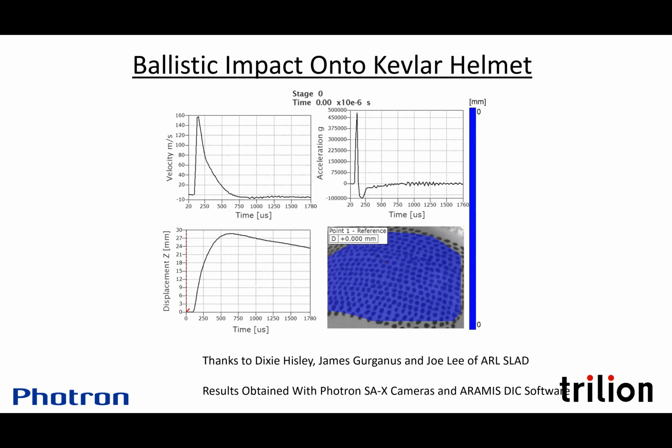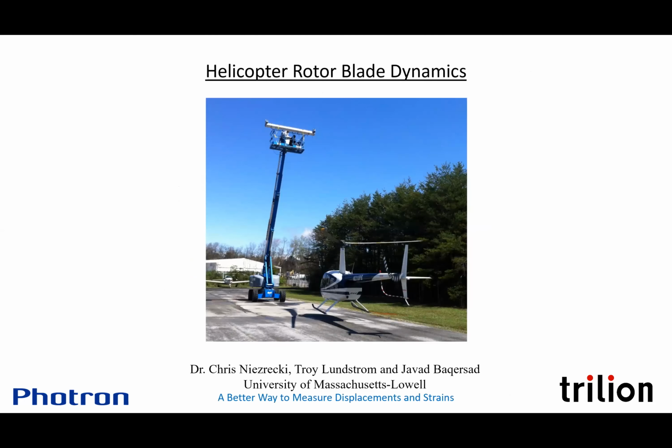ARL SLAD, Dixie Hisley, and James Gerganis and Joe Lee have been doing a lot of work. This is also showing our ability to measure not just displacement and strain, but also velocity and acceleration. And if you look at the G levels, we're talking quite a high G level. That's not so easy to measure with accelerometers, and so it's easy to do optically, actually.